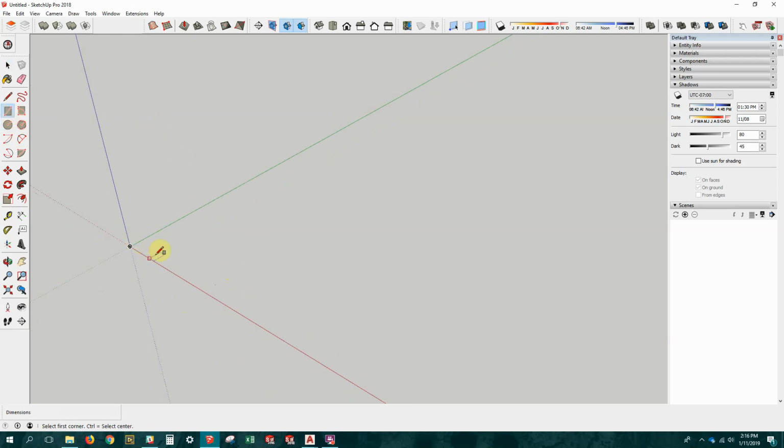First thing I want you to notice is that there's a lot of snap-to features in SolidWorks and SketchUp. So I'm snapping to the origin point you can see here. If I select my various arrow keys, I can change the orientation on which I'm drawing. So that's the first thing. Just always check your arrow keys if you're trying to mess with your orientation in a new feature.